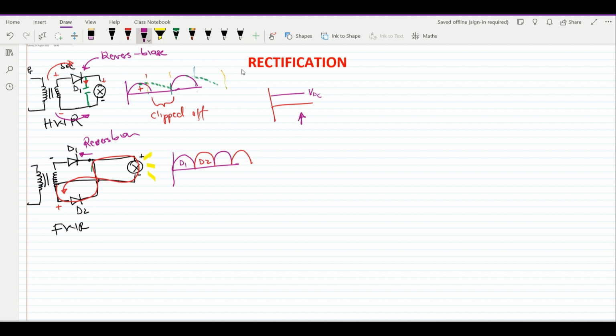Now, let us try to do the same thing here. We apply our capacitor in parallel in a full wave. What's going to happen there? Very simple. In this case, we will have a slow discharge like that. Can you see? So slowly we are approaching what we want.